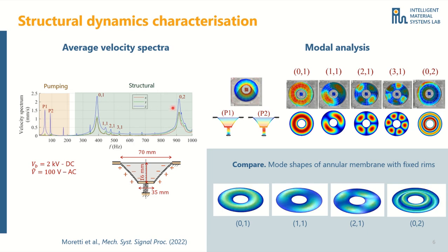And then there is a higher frequency region in which the central disk is practically still, and all of the motion comes from structural vibration of the membrane surface. These two different vibration regimes exist because this central portion has a mass which is much larger than the membrane mass itself. Therefore, this disk barely moves at high frequencies.